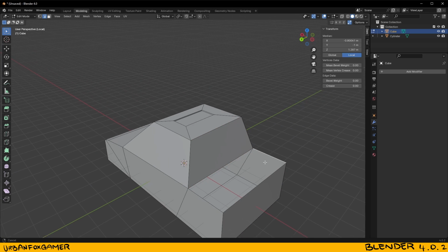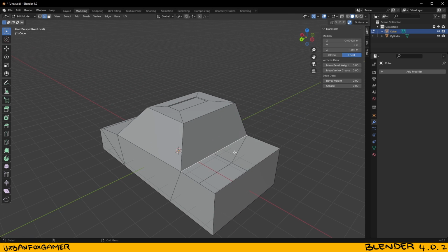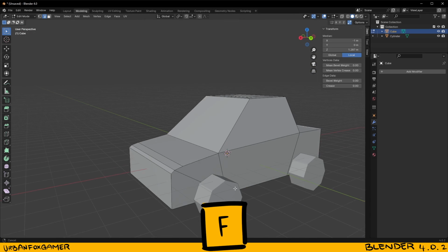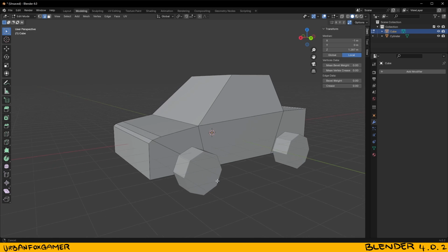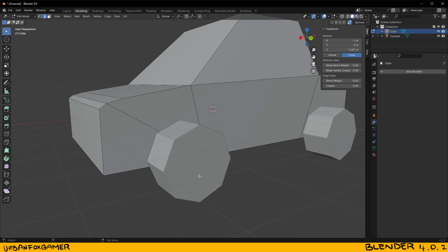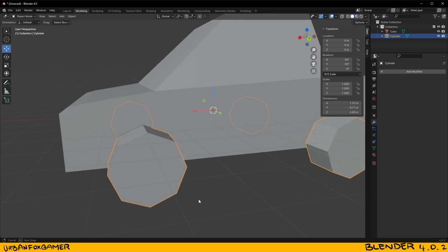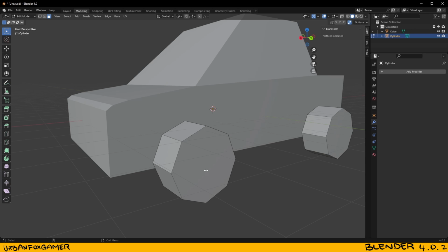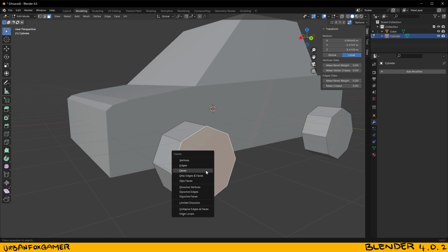Now the fill tool is technically just adding polygons. So if you press F, it will fill that hole. Going outside of isolation, we are pressing Alt Q. This is noticeable in the workflow if you press F. Let's just say this one, these wheels. I'm going to delete this face. So 3, click this one, delete face.